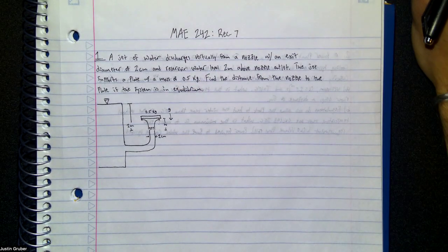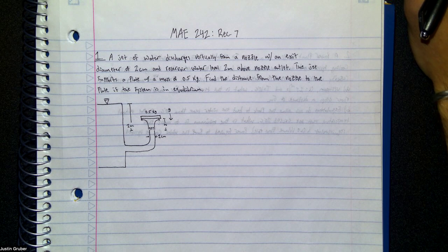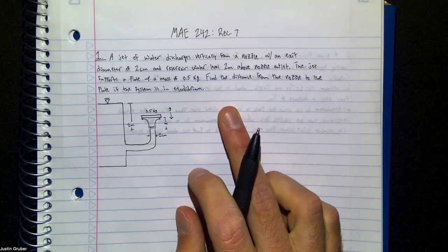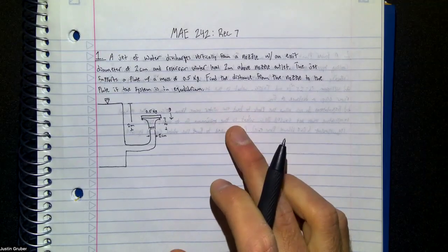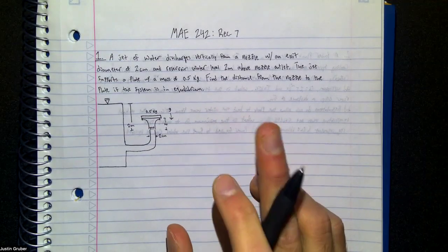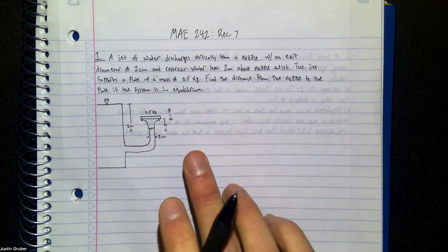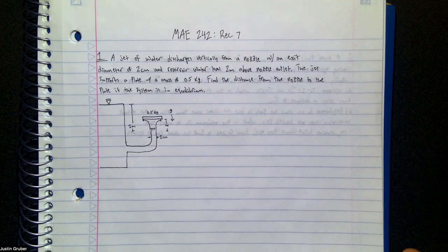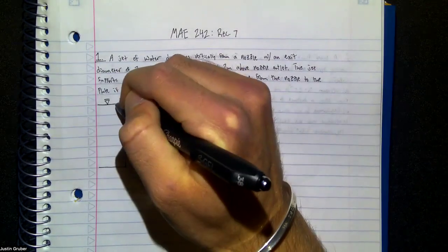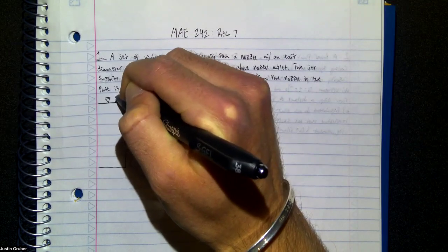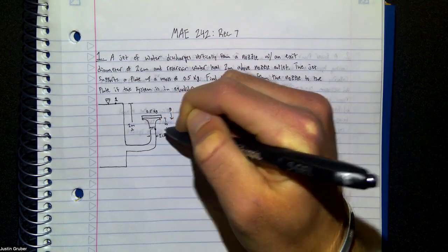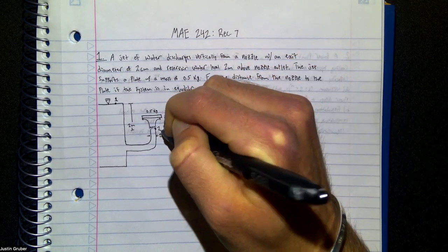Okay. So first things first, I'm not going to write my assumptions down, since we're going to be using Bernoulli's principle, it's got to be steady, inviscid, incompressible, uniform, all that stuff. There's no work being done on the fluid, right? So if you look at this whole problem, we're going to label some points that we care about. This will be point one right there. Some point right at the nozzle exit, we'll call that point two.